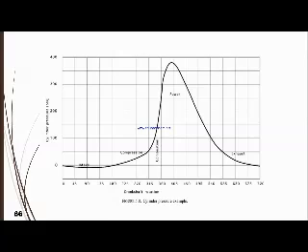This is an example of the graph of a four-stroke engine. When they suction, the reading is below zero because of the vacuum for the intake, and then during compression, pressure develops, and when burning, maximum power develops, and then when the valve opens, you have low pressure and exhaust gas.